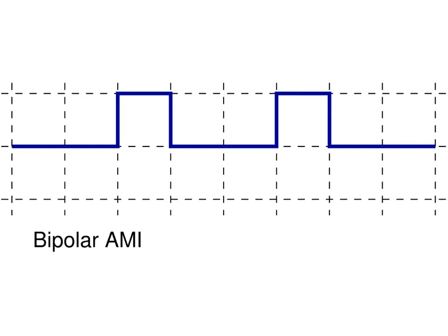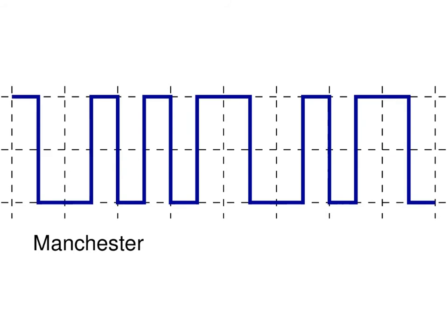So this is an advantage of some schemes, including bipolar AMI. If there is an error, the receiver can detect that. So in this case, if the receiver receives this signal, it knows at this point something's gone wrong, there's an error in transmission. Either it will take some action to respond or to inform the transmitter that there's an error and try to fix that error. So some schemes have inbuilt error detection, including bipolar AMI. We'll see some other advantages and disadvantages soon.